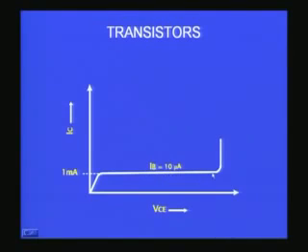current remains constant. And if we go beyond some limit, a very large voltage VCC, then it might even break down, and then there will be a very large current flowing without any change in the voltage VCE. So this is one single characteristic for one single IB value. When you vary VCE or VCC continuously, you get one such graph.